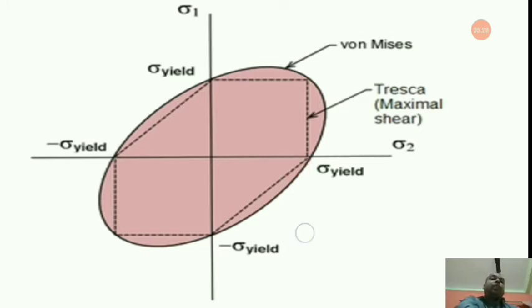But if somehow the stresses developed during hammering or extrusion or whatever, maybe cup drawing or bending, hot working or cold working, if your stress crosses this point, sigma yield, and comes here, then it has a chance to deform. Okay. And it will eventually develop cracks and afterwards it will break. So after this point yielding will take place.